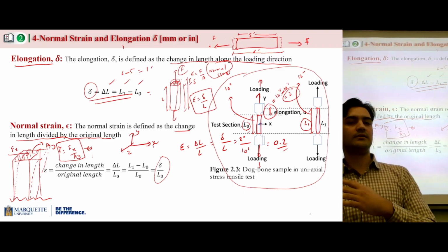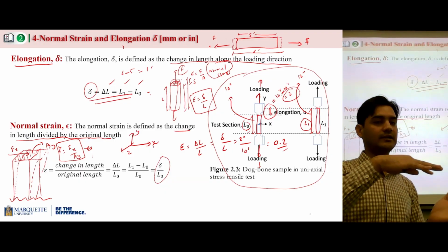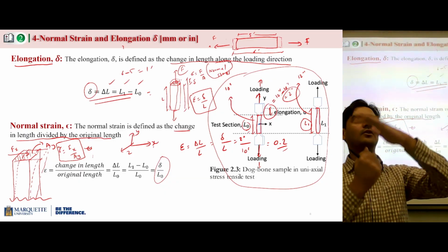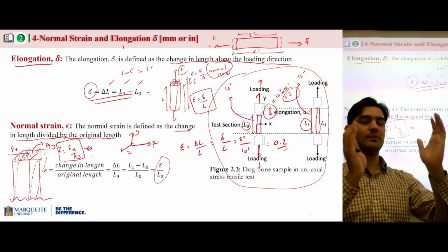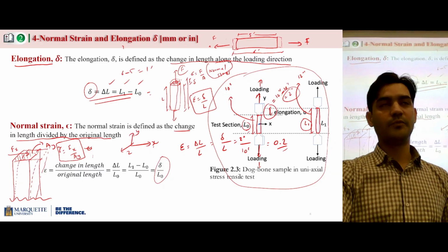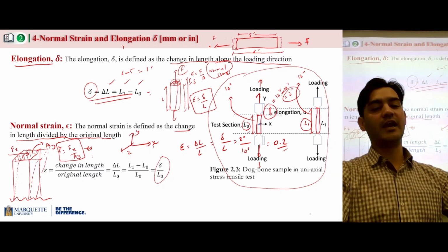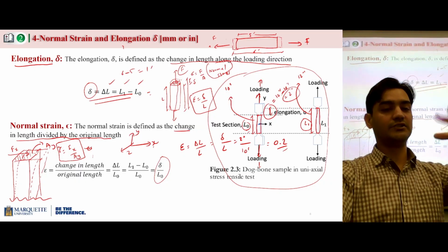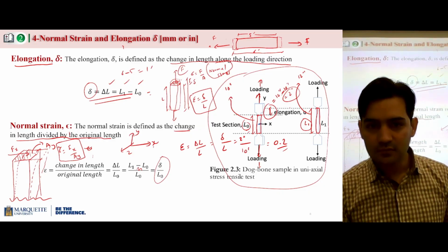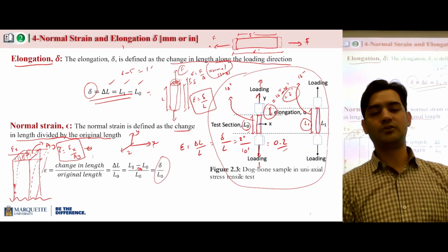If you apply a shear force, you're going to have shear stresses in a member, and it will change the shape. It will not elongate or compress the member, it will change the shape. So because of the shear stresses, you're going to have changes in shape. So it's going to create an angular distortion. So it's going to create some angle of distortion.